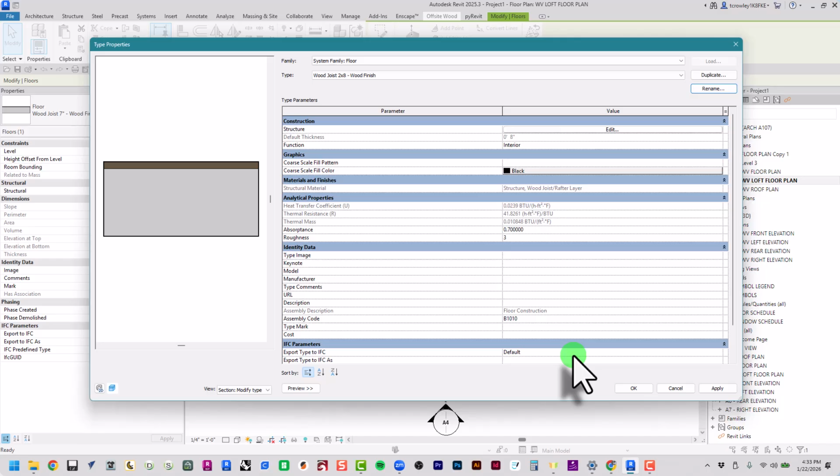Or we can fatten up the framing members to be 2x6s or 2x8s. So our span tables will give us a really good starting point as to what our framing members are, depending on the span that they have to take over.